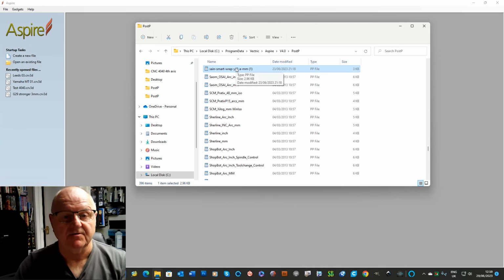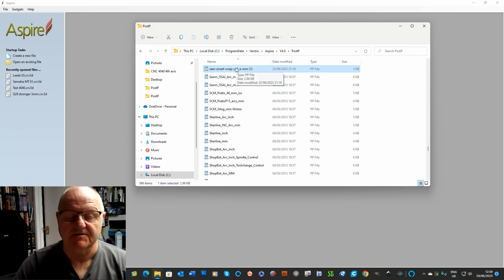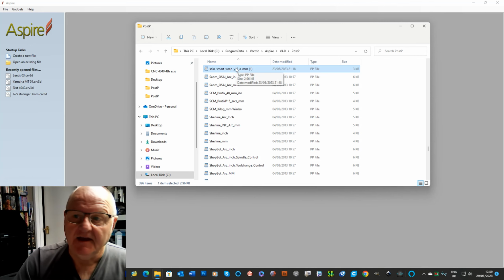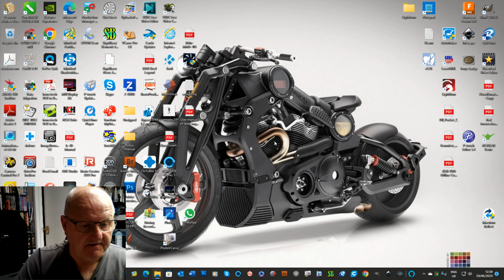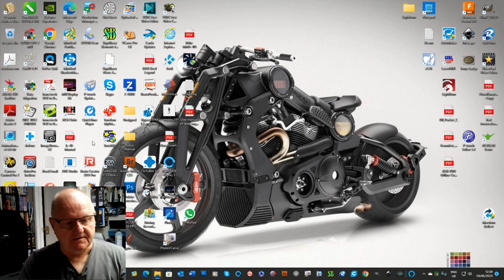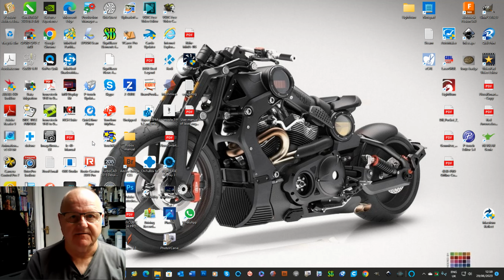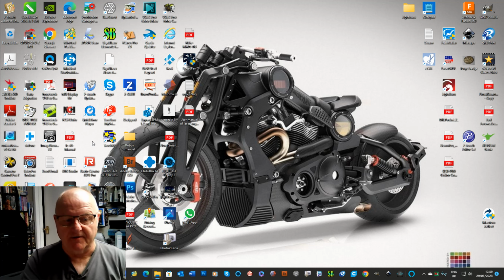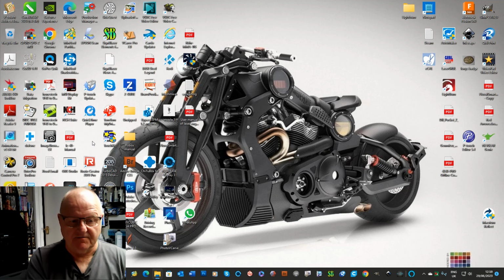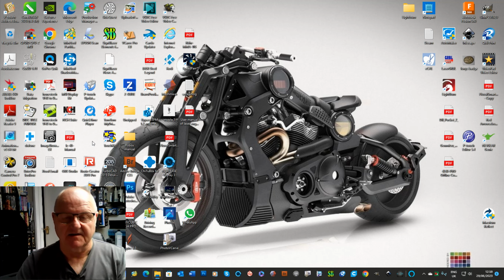Now mine's actually been done. I will show you the file with how it's worded, so you know how to identify it. Now you click out of that and you go back out of Aspire, and then once you open Aspire up again, or VCarve Pro, you have to come back out in order for it to be saved. So you can't operate the program as soon as you put it in. You've got to close the program and then open it up again, and it saves it, and then it shows it on your post processors.